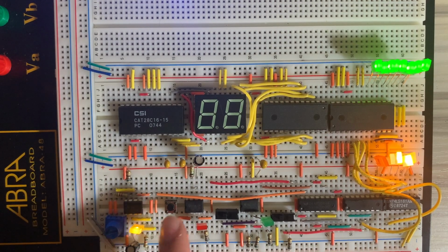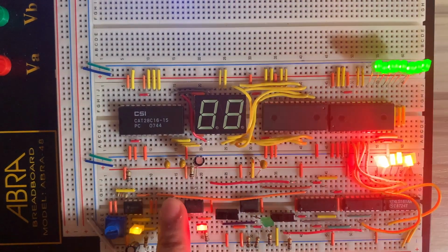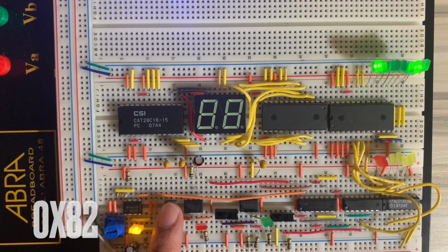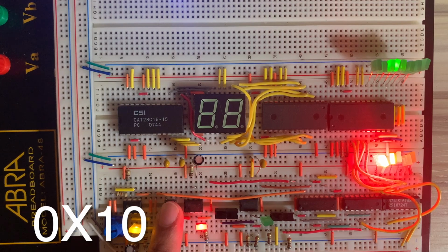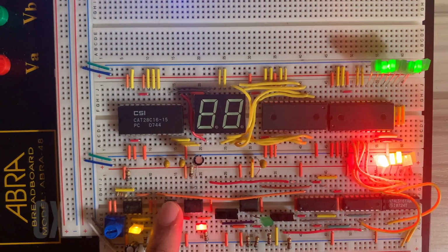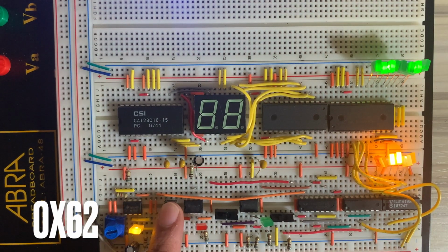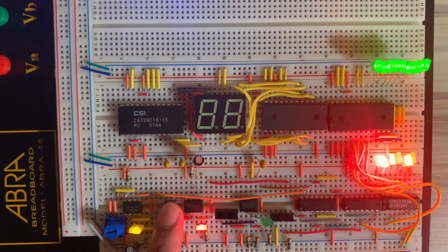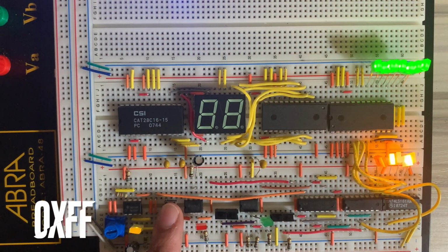So if I use this switch right here, I will pause the program, and if I click this button, which is the clock pulse, in monostable mode, it will advance the code onto the next line. Here is the first line of Feinberg's code, which is 0x82, then 0x10, 0x21, 0x62, and finally 0xA0. And then the remaining lines are all 0xFF.